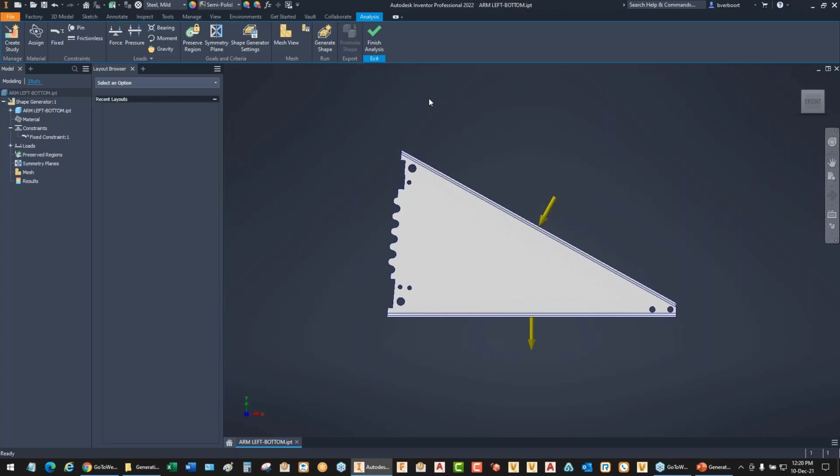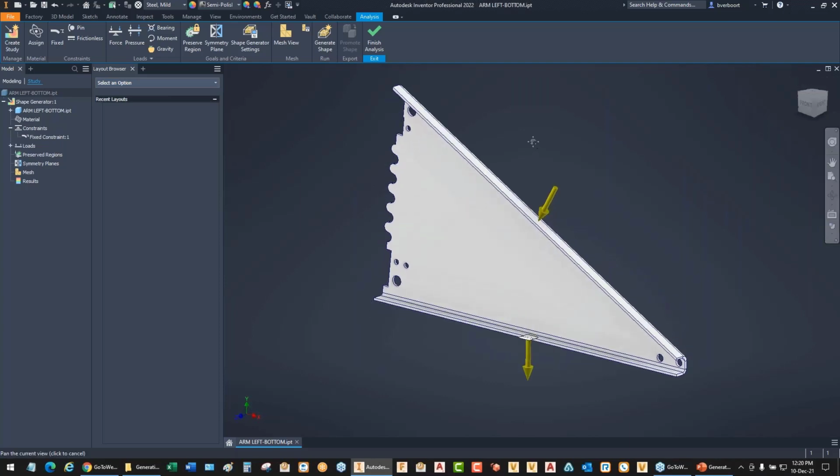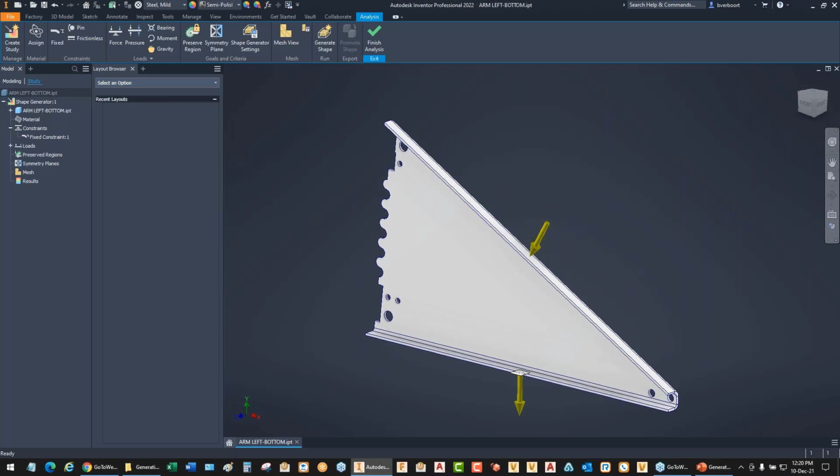These are areas we want to make sure don't get modified or interfered with, that the generative tool will stay clear of, and won't be part of its process. So we're really just excluding things that are fine the way they are and need to stay the way they are. Those are obviously things like mounting fasteners and locations and holes for the fasteners to run through.